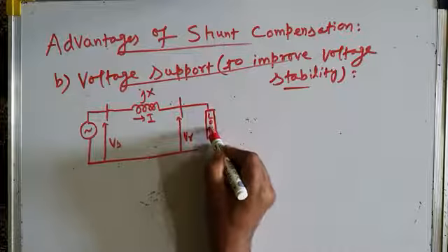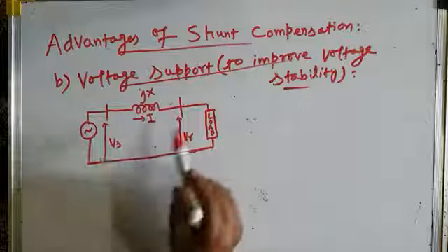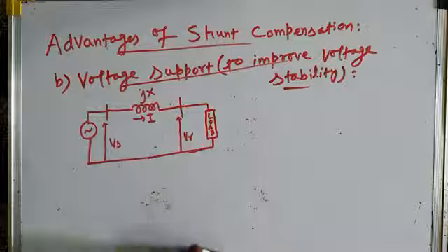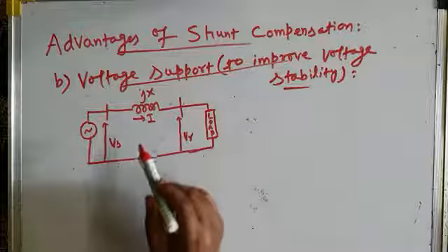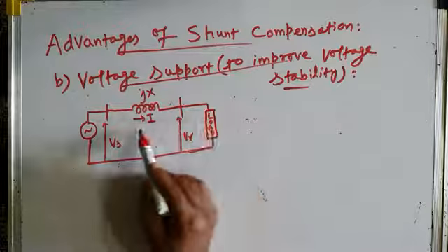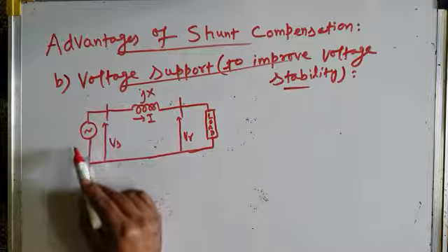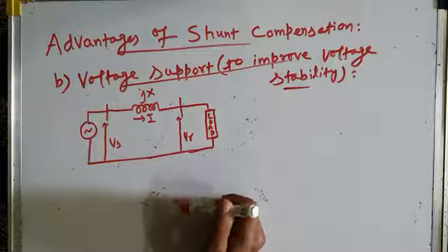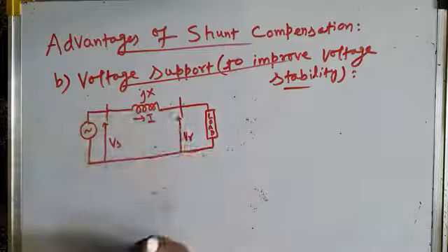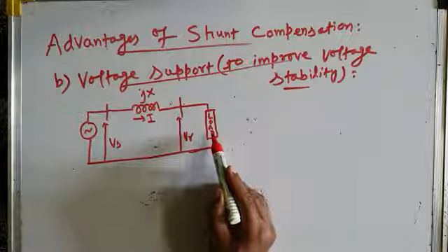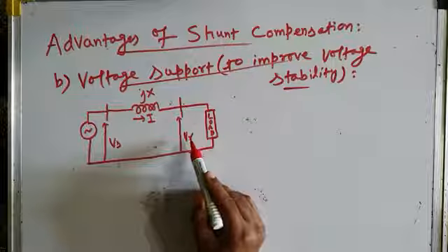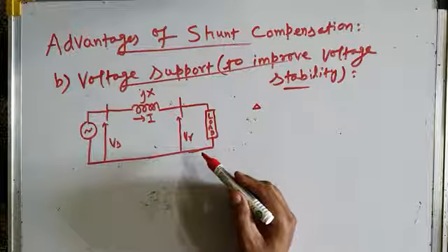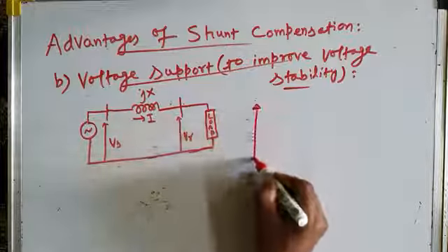So this is a radial system, where over a transmission line power is carried, line reactance is jX. The current carried by the transmission line depends upon the load, and it is I. Sending end voltage, or voltage at the generation side, is Vs, and load voltage is Vr. So this is an uncompensated radial line feeding a load with load voltage Vr. Now let me draw the graphs showing receiving end voltage as a function of power carried by the transmission line.